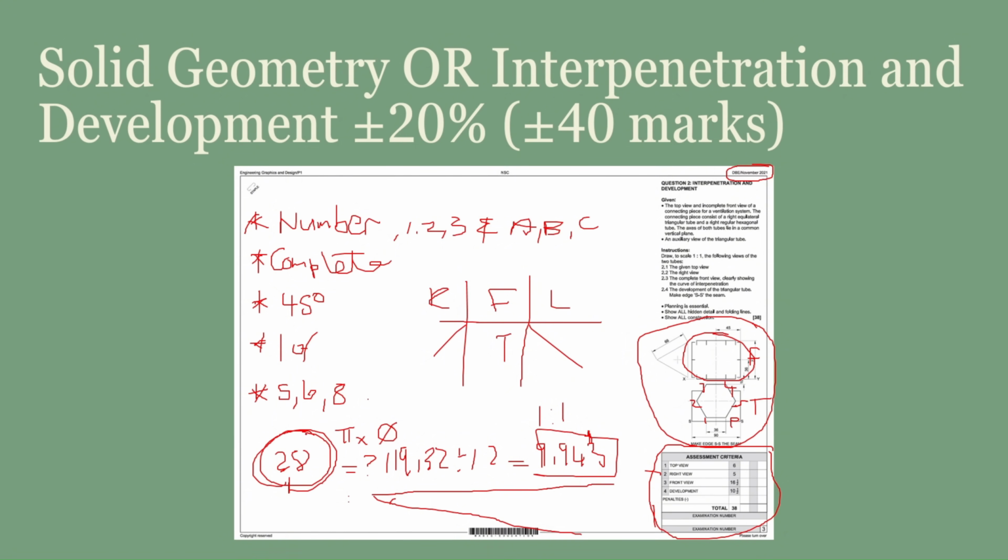Why 12? Because with a cylinder or a circle, like you did with solid geometry, you need to divide the circle into 12 parts. And you'll do this by using your 30-60 degrees. Now I'll make 12 points on this line, each 1 centimeter in spacing. The last point down here, you will connect with the end point of that line.